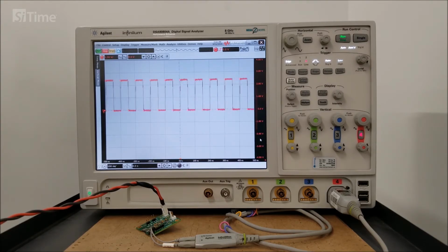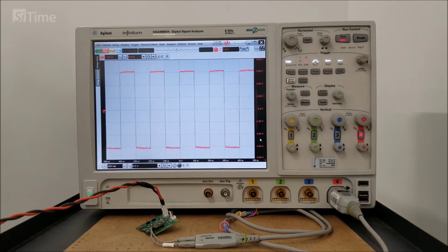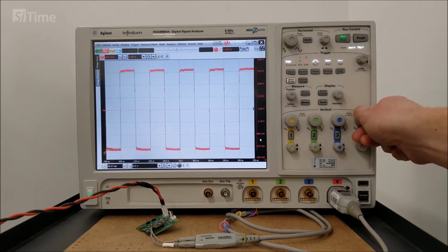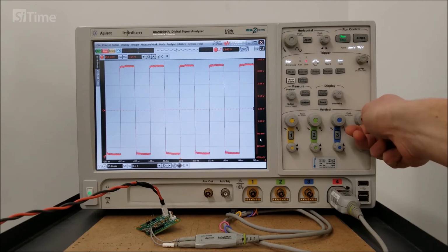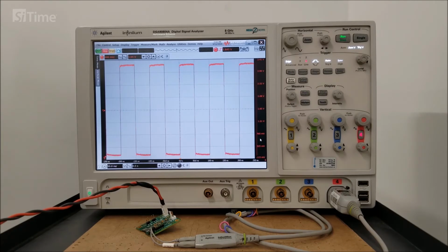For the initial oscilloscope setting, we can use the autoscale option. We recommend to stretch the signal to fill the maximum of the vertical screen scale, but avoid signal clipping. This will provide full utilization of the oscilloscope ADC range and minimize its quantization error.